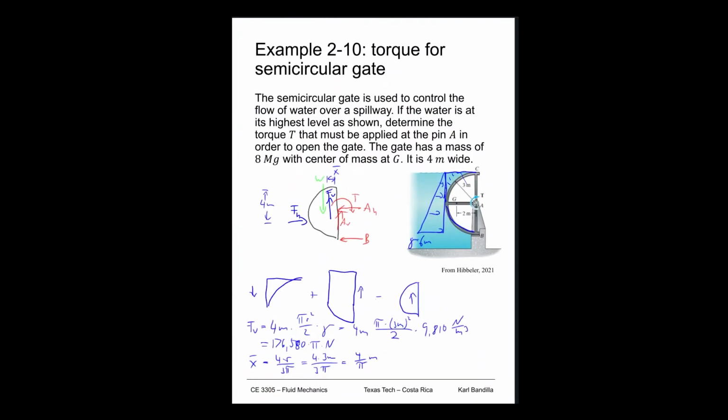All right, what else do we have? So we have all that. Then the reactions we want to find, the torque we want to find. So let's see. All the rest are unknowns. So we have the torque and the 3 support reactions, which are 4 unknowns. Of course, that's not going to work. We need to have more information. What is the extra bit of information that we can find?